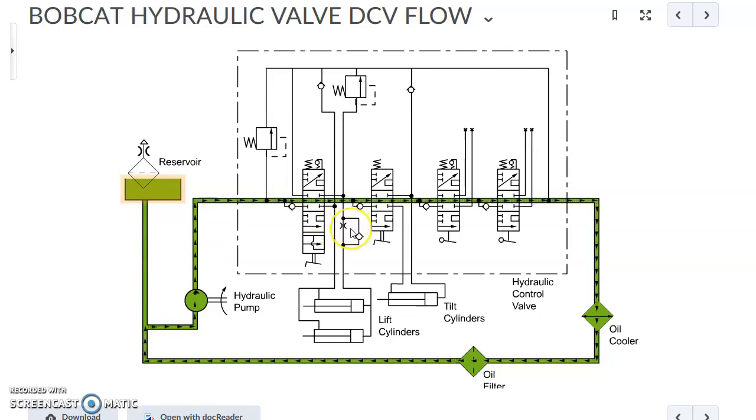That's common on a skid steer loader that is on rubber tires, because they're fairly tippy machines. They don't want the operator lowering the loader frame too quickly and then stopping. What that can do is have the machine rock forward on the front tires and tip the machine, and you've got an operator hanging in the seat belt, not in control of the machine. If the machine's on tracks, then you may not have a one-way flow restrictor, because the machine's got a more stable platform that it's working on. It's not going to be rocking so much on its undercarriage.